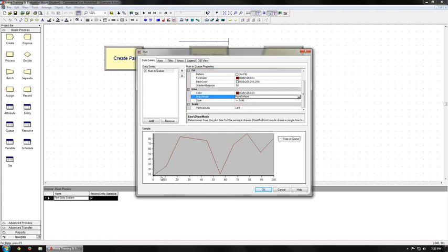And this kind of implies that, say at time 5, the value is this value here, about 15, whereas that may not necessarily be true, because remember, we're working on a discrete event-based simulation here. So if you pull this down and change it to stairs, you'll notice that the graph looks quite a bit different. It looks like stairs going up and down.